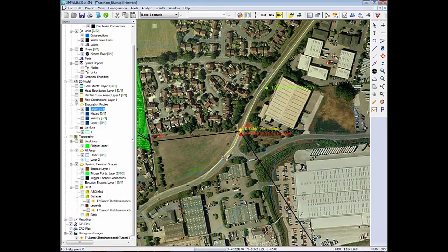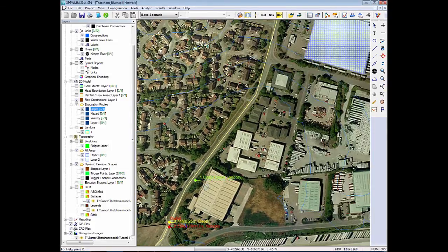When I struck the line along the profile, we've got about 600 to 700 meters distance to walk. So that's going to take 5 or 10 minutes. So really what this is telling me is that we can tell people, you need to run emergency evacuation drills from that building and make sure that, from the moment the alarm is sounded, you have, say, 30 minutes available to then move from the building up to the muster point. That would be a part of our routine fire drills.